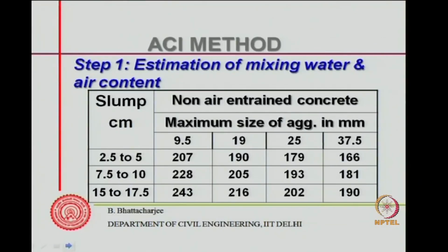This table has two parts. The first part is related to the mixing water, and the second part gives you the amount of air entrainment. So you determine the amount of air content and mixing water together from two tables.